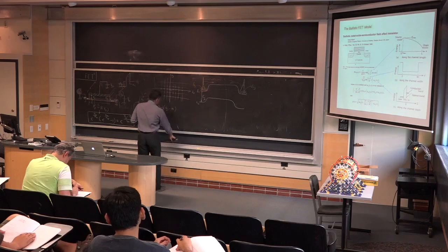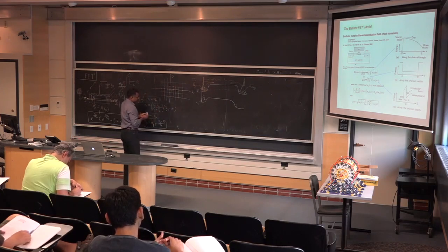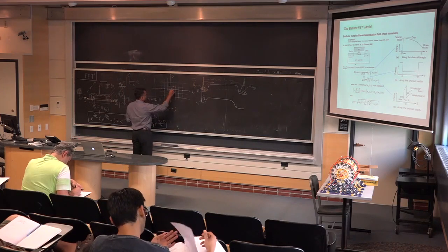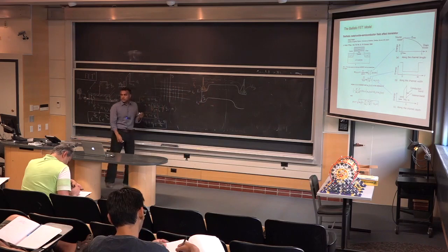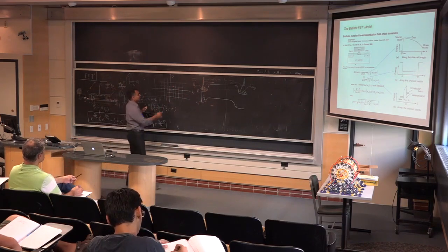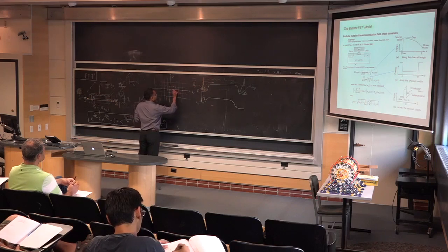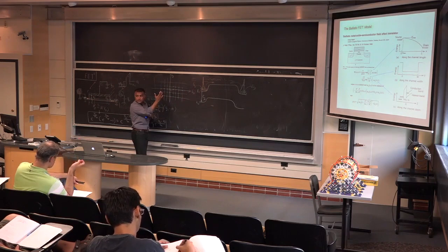And in that case, what you realize is in the K space, you have a very interesting picture now, right? In the K space, you will fill the modes that are moving to the right, and they have all come from the source. Does that make sense? All the electrons that were filled and they're moving to the right, what does that mean? It means the Kx is positive. Right? Kx is positive, meaning that's the electron that's moving to the right side.